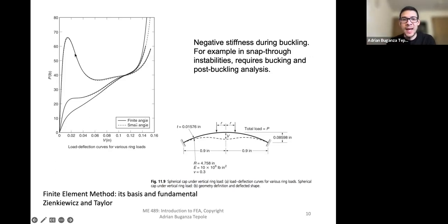What happens is that your stiffness becomes negative for a little bit before becoming positive. That means that there's a very large displacement without an increase in force. So when you hit that critical load, there's suddenly a big change in the deformation. You've done this for 323, where you have columns and the Euler beam buckling of columns, where you push normal, and then at some point it will buckle. And at that point where it buckles, the stiffness is basically zero because there's a large change in shape without extra force.